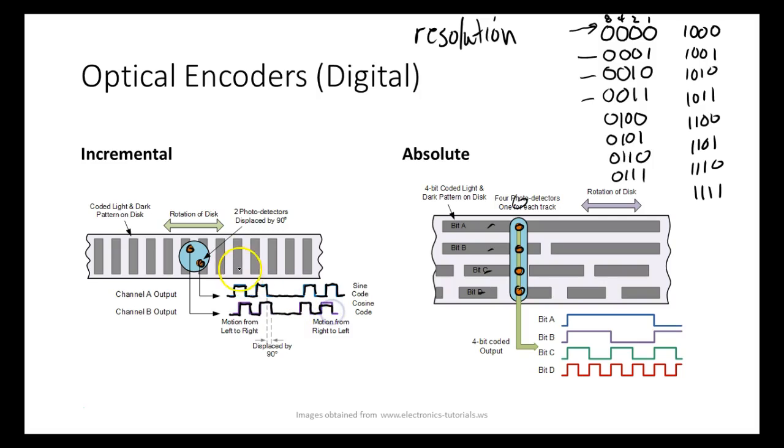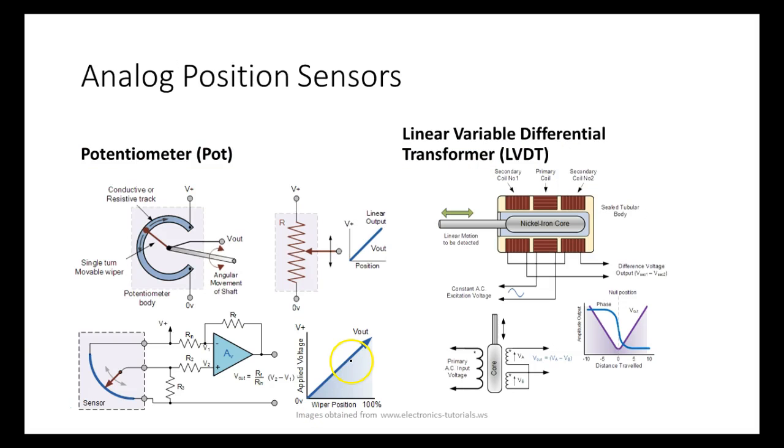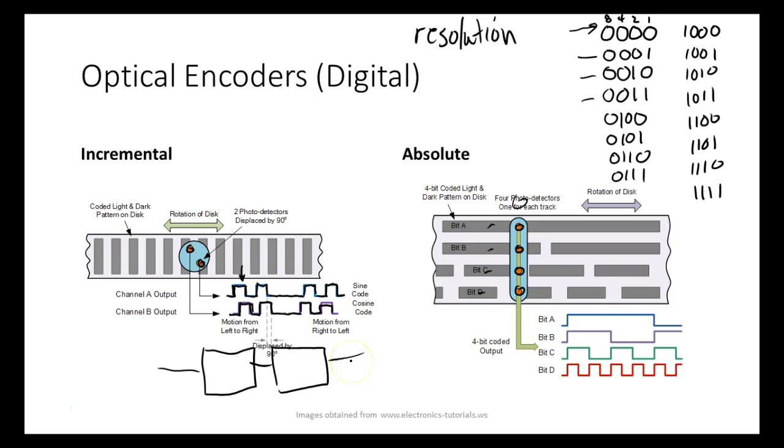Now we have two options. We could use one of them as the position, or we could actually use two of them. If we look at just edges, then we could count the edges. What we have to do, guys, is take the output of this and run it into digital counters, and these counters are going to count for us. Does that make sense? With one pulse, these counters would count one. Second pulse, they would count two.